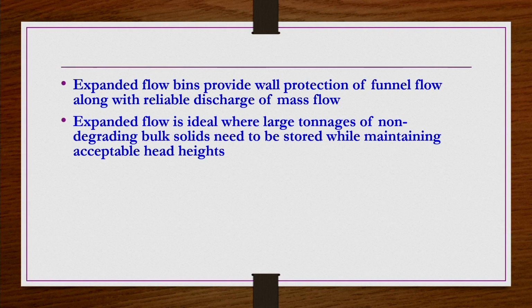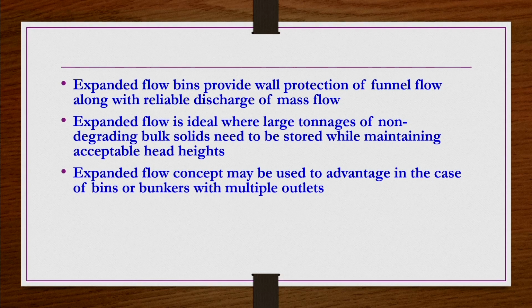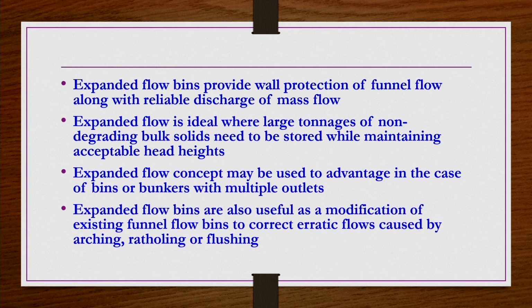So, expanded flow is ideal where a large tonnage of non-degrading bulk solids needs to be stored while maintaining acceptable head heights. The expanded flow concept may be used to advantage in the case of bins or bunkers with multiple outlets. If you have more than one outlet, then this concept is also going to be useful. Expanded flow bins are also useful as a modification of existing funnel flow bins to correct the erratic flows caused by arching, rat holing or flushing that we have seen in the case of funnel flow.